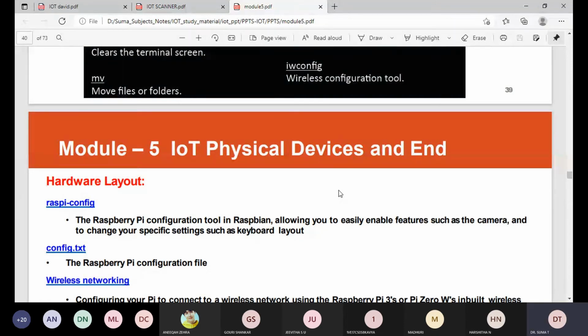The OS installation. Suppose we want to install the operating system, we have to follow some steps in order to work on the installation of the operating system. Go to the Raspberry Pi Foundation website and click on the download section. Then click on the NOOBS download zip button under NOOBS offline and network install, and select a folder to save this zip file.